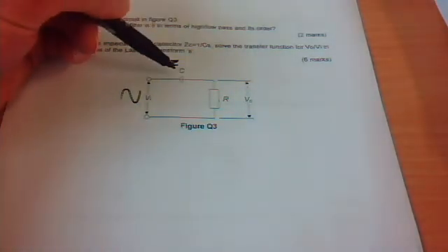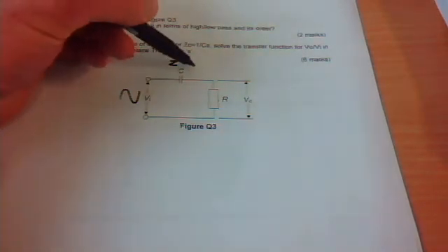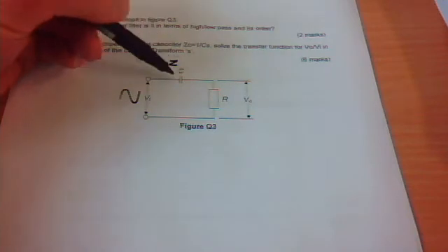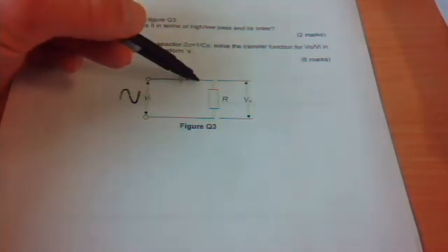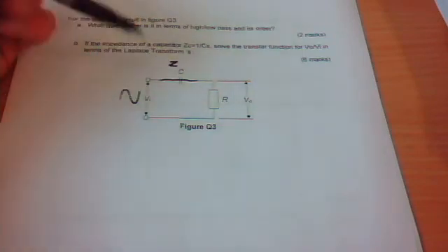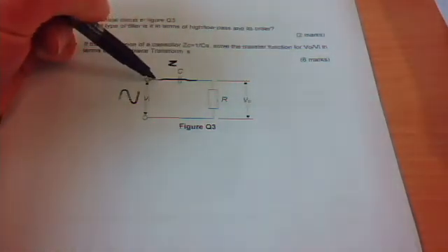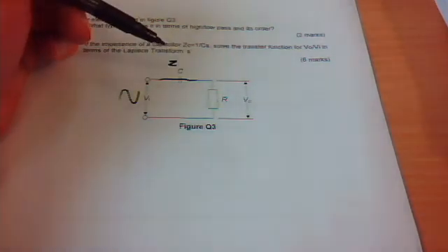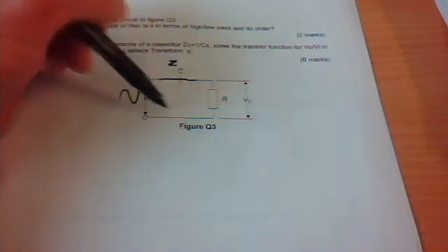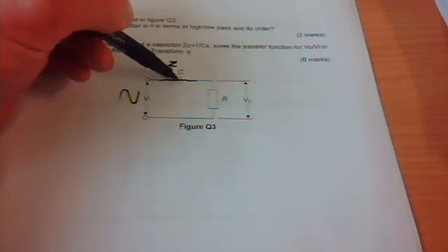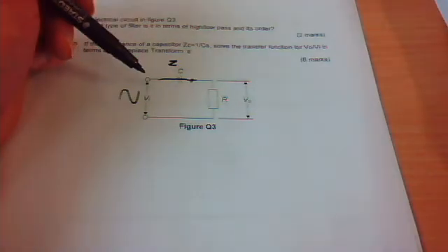And the impedance of a capacitor lowers when the frequency increases. So if we get a higher frequency through this circuit, then this becomes almost like a straight wire, almost like ignoring the capacitor. And if there's a very low frequency going through this circuit, then the capacitor acts as an open circuit. So it's almost like there's no piece of wire there at all.